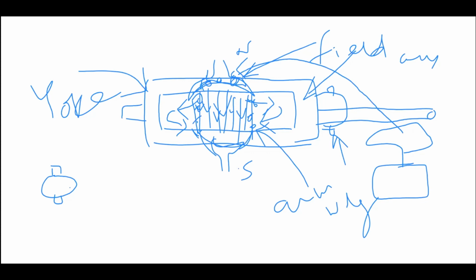But if the brushes are made of carbon, the drop is more. That is the disadvantage. But the advantage is that carbon brushes, during armature reaction and commutation, produce spark and carbon black, which acts as a self-lubricating device, so it is helpful.